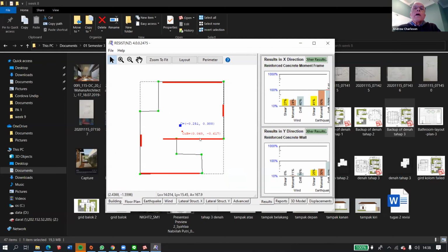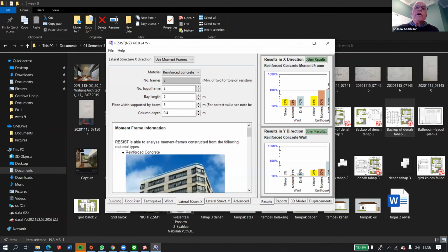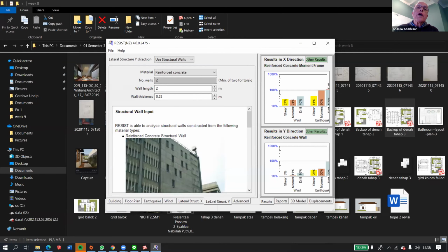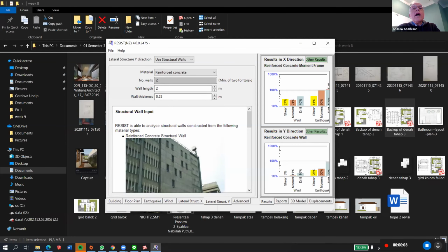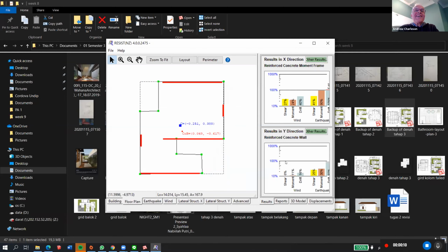And in the Y direction, your drift is getting close to 100%, which means that you've got a very economic design. You can't make those walls any shorter than 2 meters. Otherwise, your structure will be too flexible. So look, you've done a very nice design for that house. Thank you, but still a bit fail.